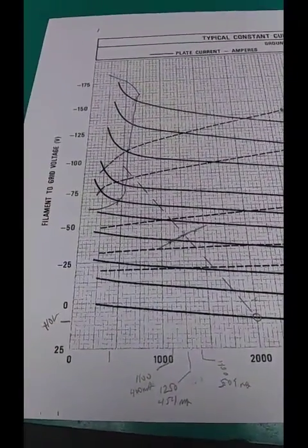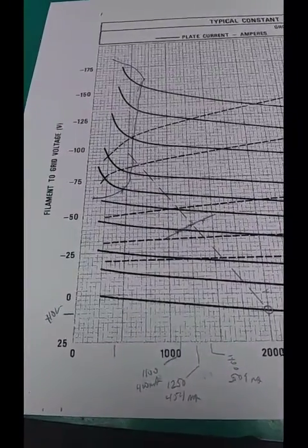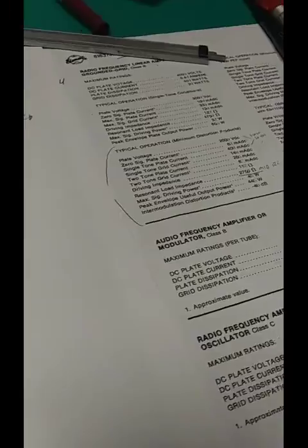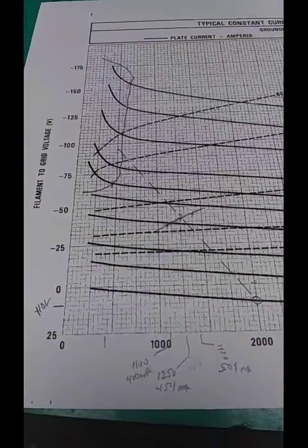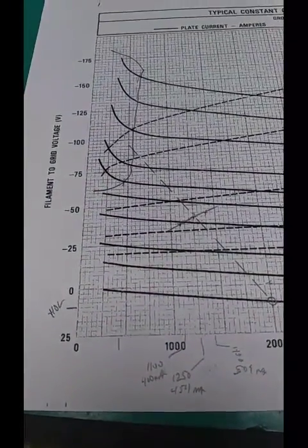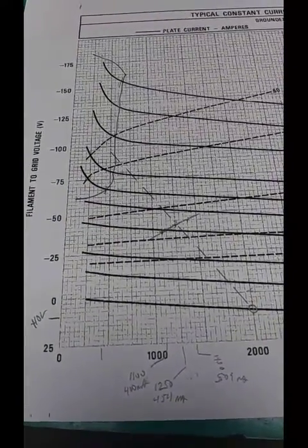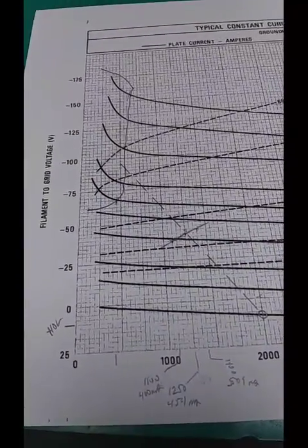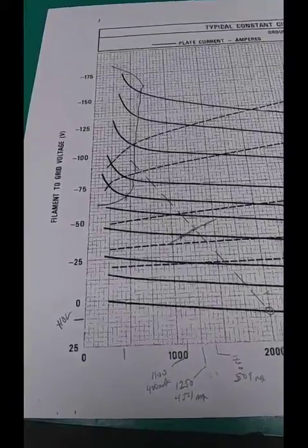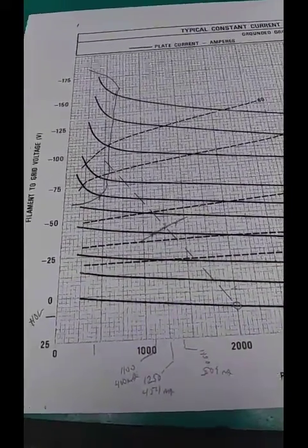If I really have engineering knowledge, I should be able to calculate this to be very close to working the first time, especially because they're giving me much of the information. But I should be able to go calculate the output network, which I've done. I should be able to calculate the switching, the reflection coefficient, and all that with the relay switching, which I did. See the impedance matching video on this channel. And be able to set up and tune the input correctly, which turns out to be a much more difficult problem than any of this. I'll do another video on that later.